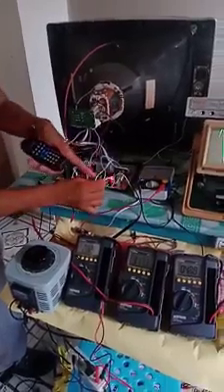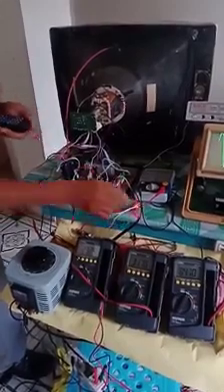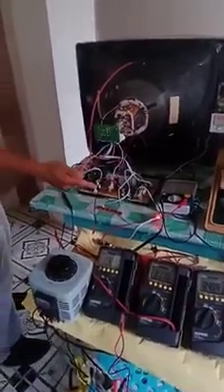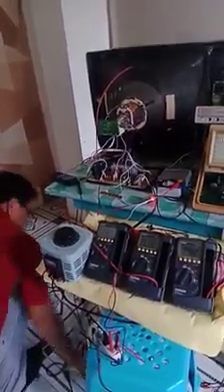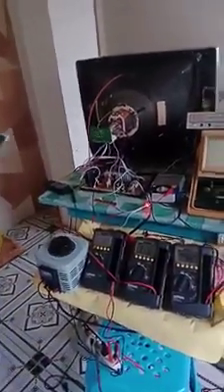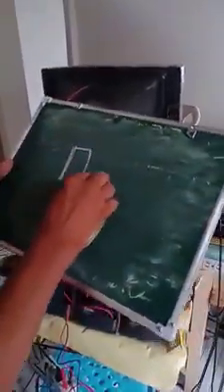Infrared transmitter, or remote control. Then we have here an infrared detector, an infrared receiver, that detects or receives the pulses being transmitted. The pulses are actually the binary information, being carried by 38 kHz. So this 38 kHz, by the way, class, is a carrier. We have here a series of pulses.